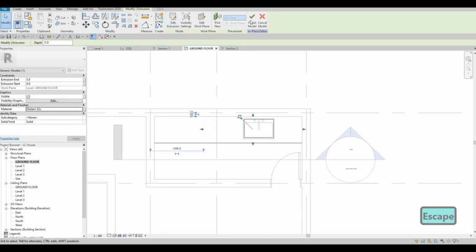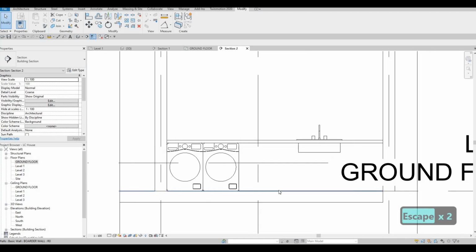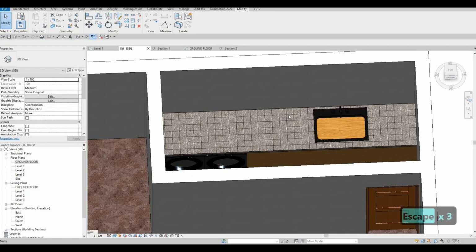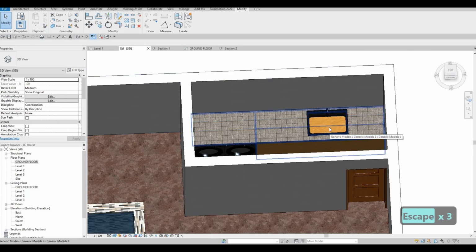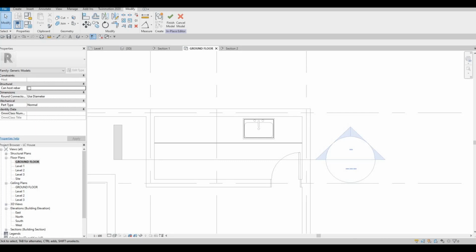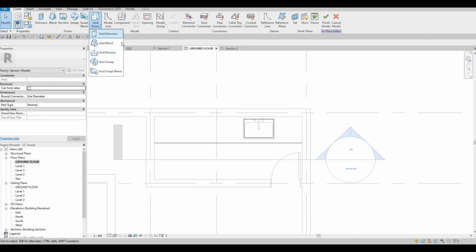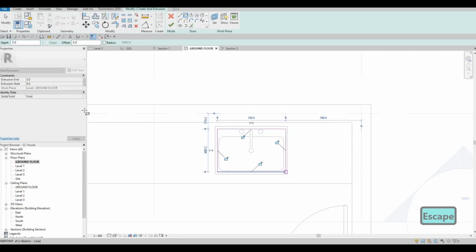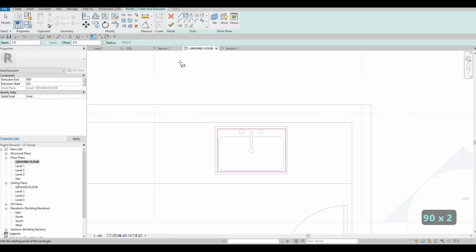Click finish and then finish, and then look at it from here. Select that. That is our wood material. So now we just need to void that part. I think it's better to edit in place and then void extrusion, and then let's void extrusion R on this part, and then we should put this one around 900.